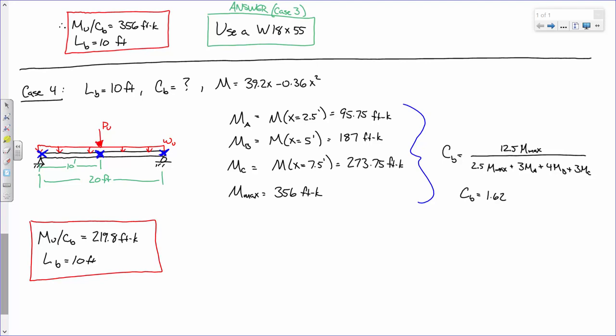That can happen. So now what I want you to do is go back to table 3-10, to the beam charts. Look up that spot again and give me the next shape. Okay, so I'll write this down. Trial sections. The next section we got here is a W14 by 43. It's worse, it's at 261. So BMP is 261.